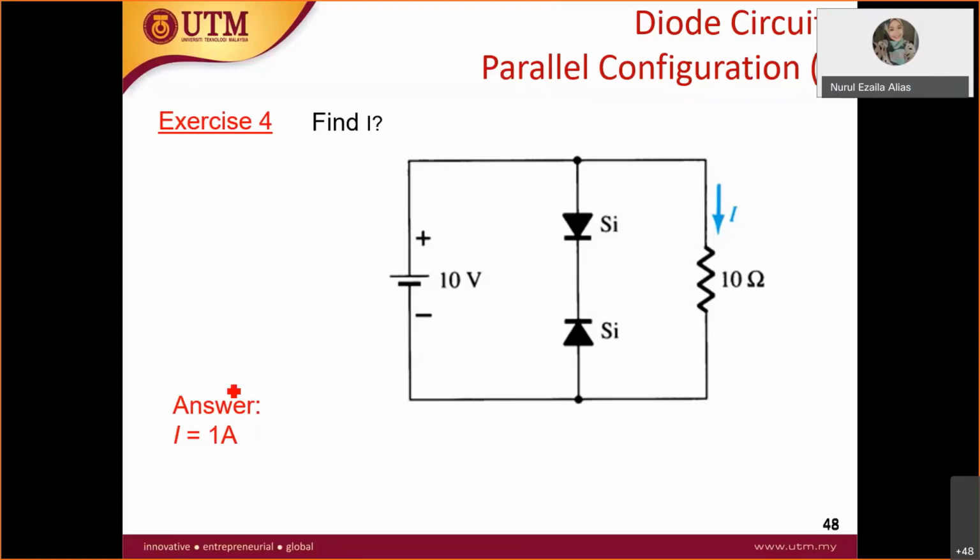So forward bias, because this first diode has the anode connected to the plus terminal. How about this diode? Reverse. Reverse bias diode, because the anode is connected to negative. So this would be in reverse bias.